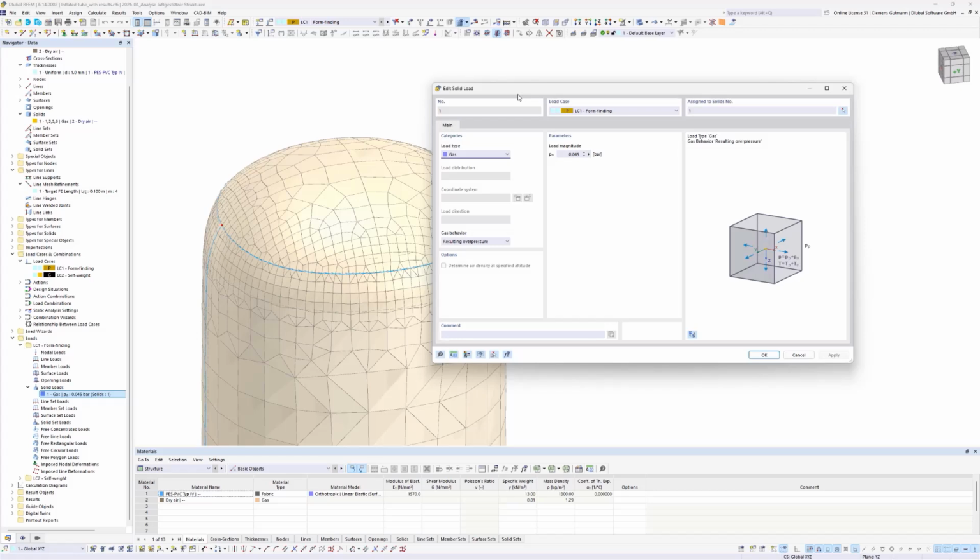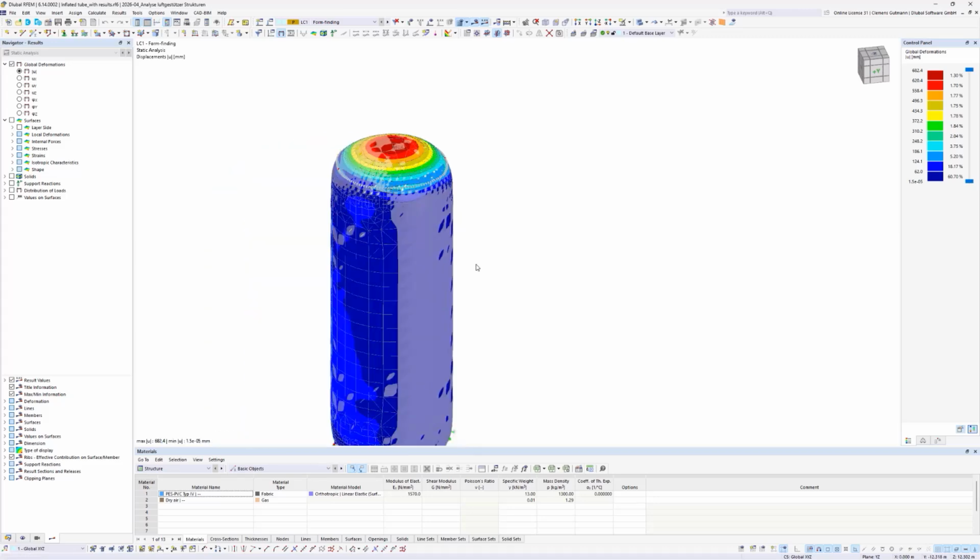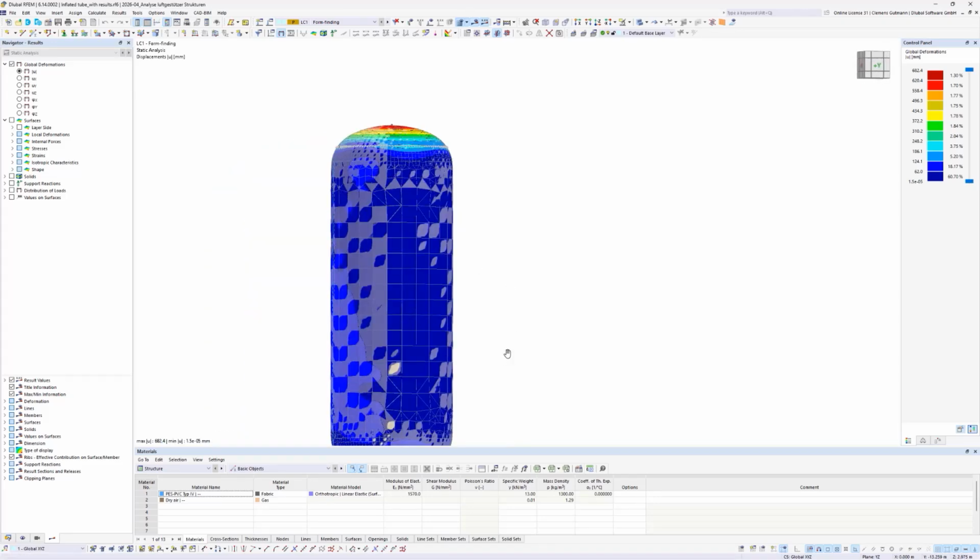You can, however, but in reality you, as I said, manufacture the rough geometry and then you inflate it, and then there will be effects to it like the creases, like the crease issue that we talked about just before. In my case, I chose a resulting overpressure of 450 Pascal, so that's 0.045 bars. And yeah, then I get this result, which looks quite realistic.